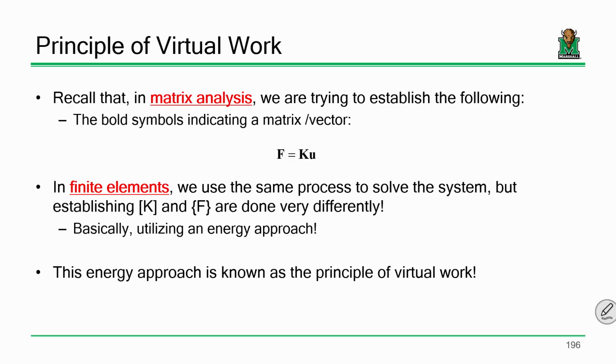But basically, what the finite element method states is we do two things. One, we make a guess based on a given element. We make a guess on what that displaced shape of that element looks like. Before we were talking about degrees of freedom, and we said how many degrees of freedom defines what the displaced shape looks like. We're going to make a guess for a given element. Then, based on that guess, what we're going to do is compute energies.